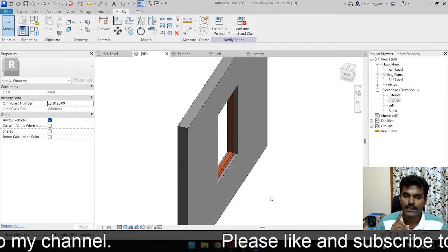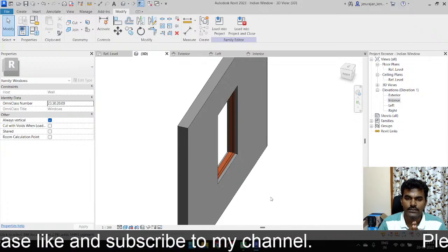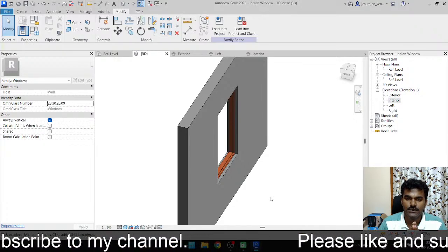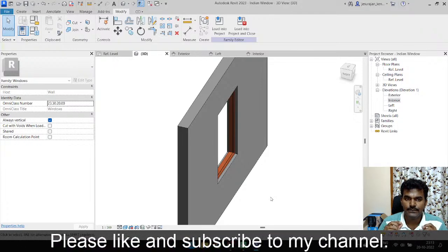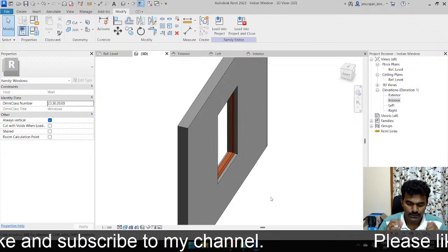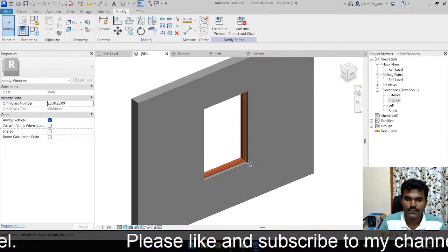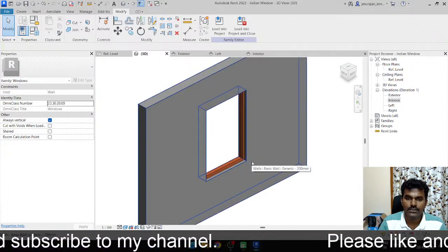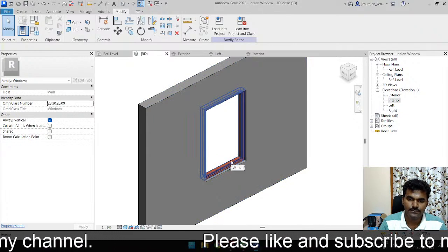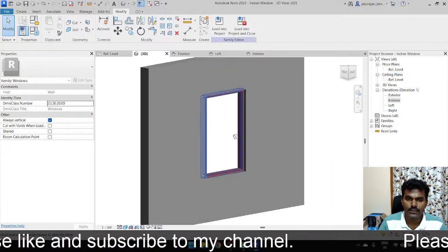Here I want to connect the steel rod. For that I should create the steel rod as a nested family. Let's stop this window frame here and create the steel rod as a separate nested family, so that when you are using it here, creating an array and all will be easy.